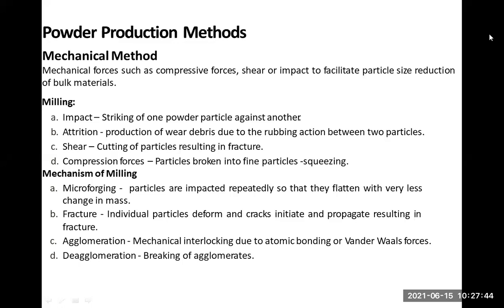So regarding mechanical powder production techniques, there are different methods, like mechanical methods. In mechanical methods, forces such as compressive force, shear, and impact facilitate particle size reduction of bulk material. That is the first thing. In the mechanical method, we have different types like milling, abrasion methods, chopping or cutting methods, and machining methods. So these are the different methods that are going to be considered.